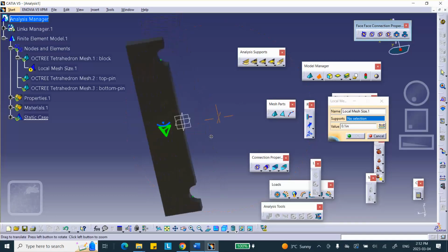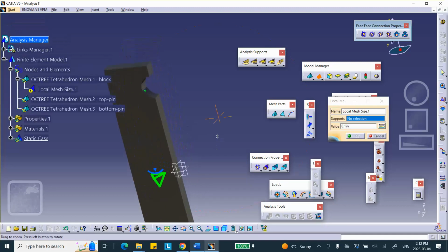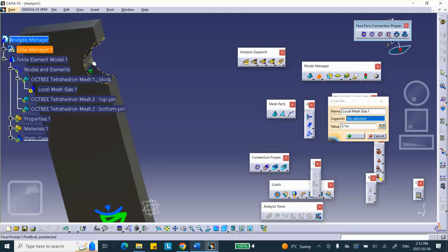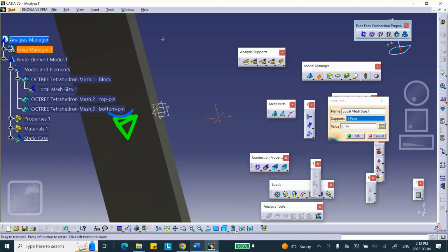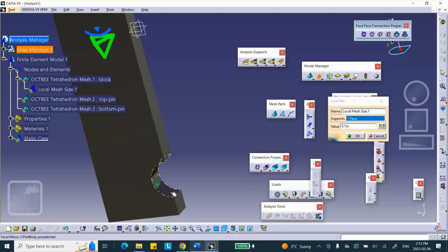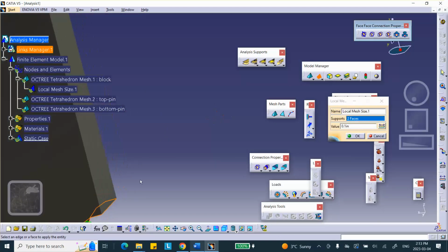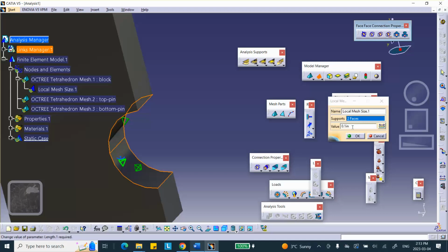And you go and select these two faces because we want to make a refinement on this face and that face. Now the size, notice that it already decided based on this number that was sitting here from the previous year maybe, or before the midterm. It uses this element size. If you're happy with it, keep it, otherwise make it bigger or smaller, whatever you want to do.